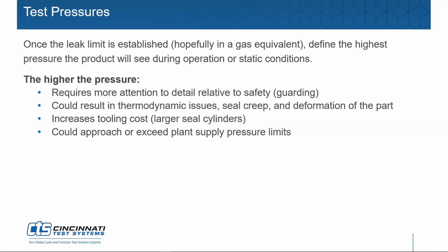Yeah, absolutely. And as we're talking about test pressures, like we mentioned, if you're testing at a low pressure and a low leak rate, you may feel, hey, if I increase my test pressure, I can actually increase my reject rate to make it easier to test my part. Well, things to consider when you increase test pressure are the safety related to large surface areas on seals. As that pressure increases, the surface area is going to see more force.